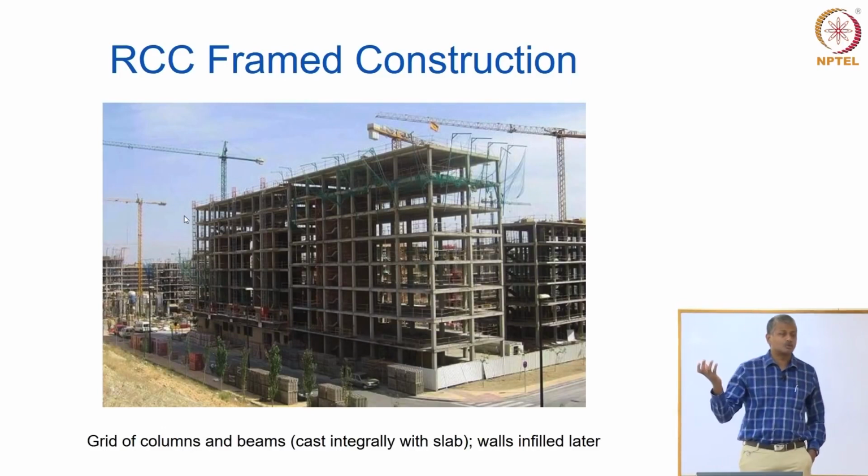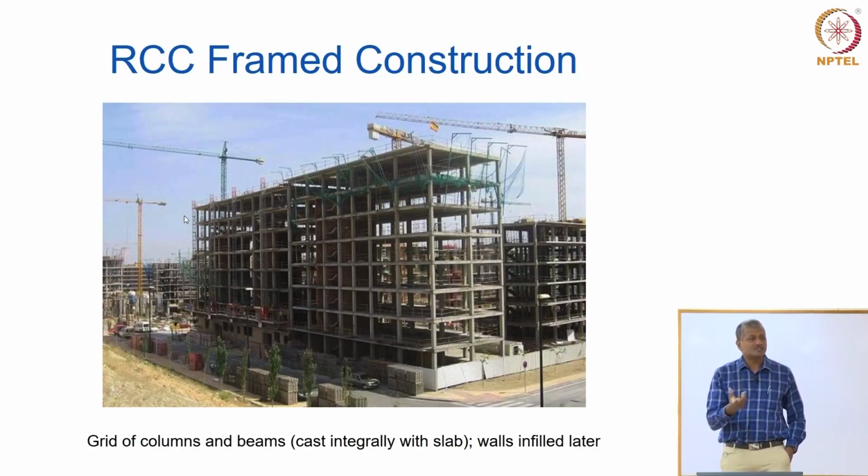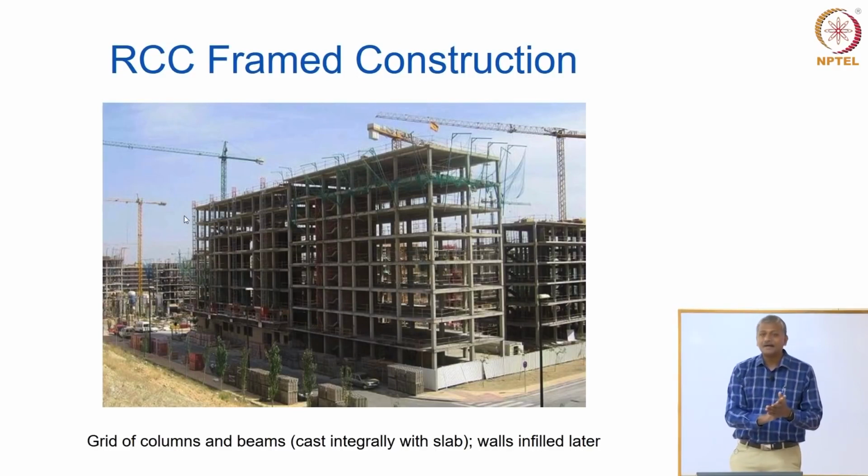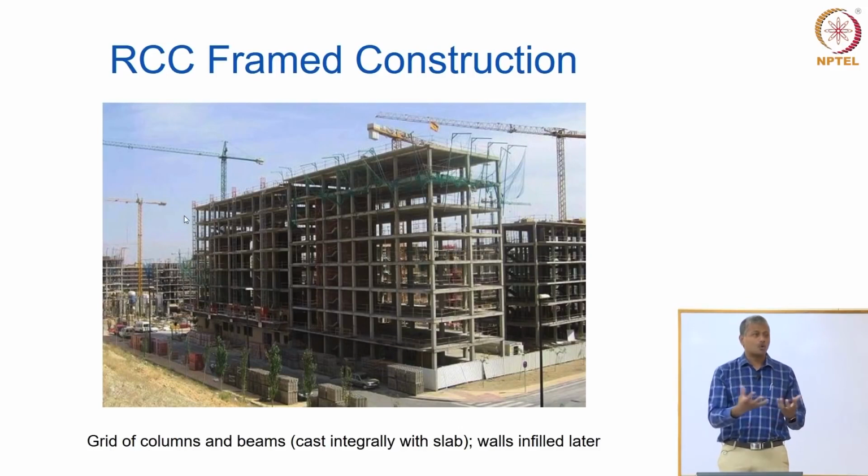And today, if you go out to see real construction projects, you will see that the wall is now being built with concretes like lightweight concrete or aerated concrete. Why is that interesting? Because if you put air inside concrete, if you make it highly porous, the flow of heat and sound through concrete is increased or reduced? It is reduced, right, because heat gets conducted much more easily through a solid than through a porous material. So, you introduce voids and gaps inside your concrete, which makes the heat flow much reduced.